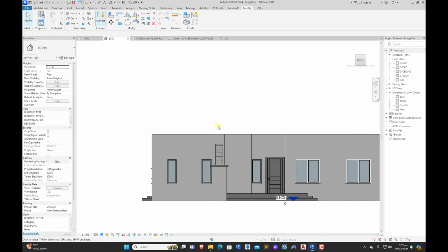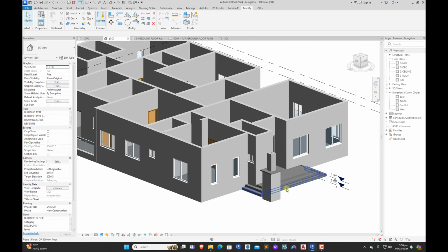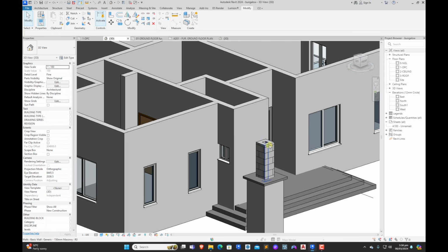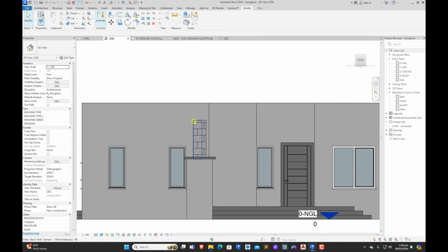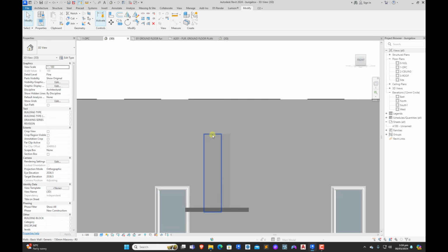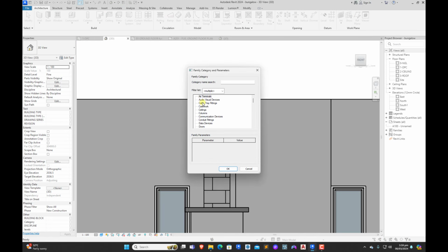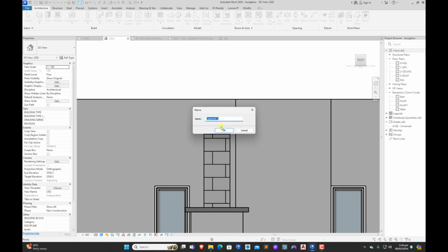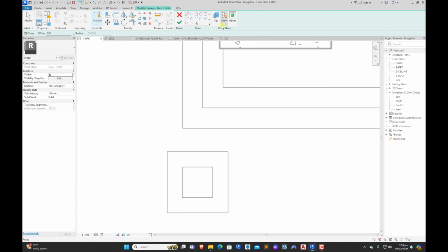Alright. Good. Ceiling level. Okay. It's coming out. So we're going to create a small sweep along the top of this column. Now for us to create the sweep, come under Architecture, Components, click on the drop-down below, Model In-Place, we click on Casework, okay, we click on Sweep, then we come to the floor plan and we sketch parts.